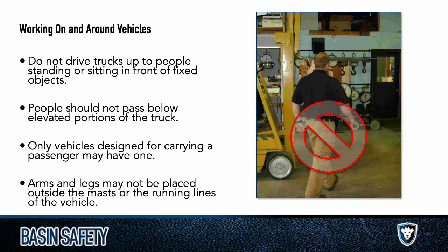You can also change, a lot of people will say, well, when I'm lifting equipment up, I can't see because it's in my way. It's like, well, then drive it backwards where you can see, right? Be a little creative there. It's not the best way, but if you can't see, it's better to operate backwards and be able to see.